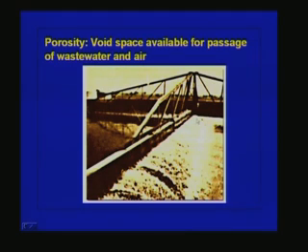It is working because of the hydraulic pressure, hydrostatic pressure available here. The wastewater will be coming, and if it can have a hydrostatic pressure of 1 meter of water, then the rotating arm will be rotating by itself because of the hydrostatic pressure. We don't have to give any external power, and this supply of wastewater will be intermittent.